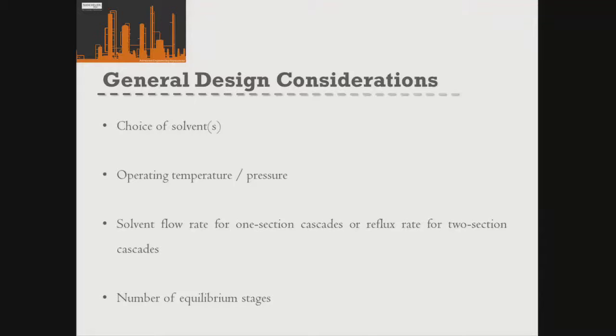So the other choices that you have, and a big choice for liquid-liquid extraction, is what solvent you're going to pick. Okay? So you want to pick your solvent based on having a good solubility with your solute, but essentially being insoluble, immiscible with your carrier. Okay? So if you look on Blackboard, there's a short few slides discussing how we would select our solvent, and they go through and show you how you would actually select a solvent.